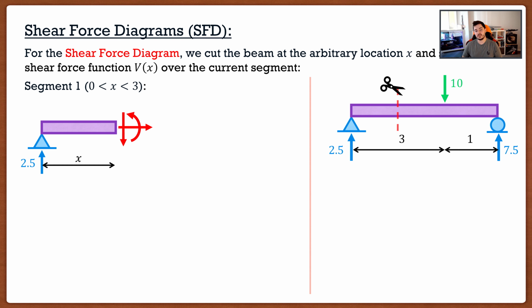Now this is important because our normal force, shear force, and bending moments are now going to become functions of x. So when I'm labeling this diagram and I look at the axial force, I'm going to say N1 as a function of x. For the shear force, I'm going to say V1 as a function of x. And of course, for my bending moments, I'm going to have M1 as a function of x. Again, it's a function of x because we cut it at an arbitrary point, but we also have the ones there, M1, V1, and N1, because we know that we are actually going to have to analyze the second segment on the right side of that point load a little bit later on. So this is why I have it as V1, N1, as well as M1.